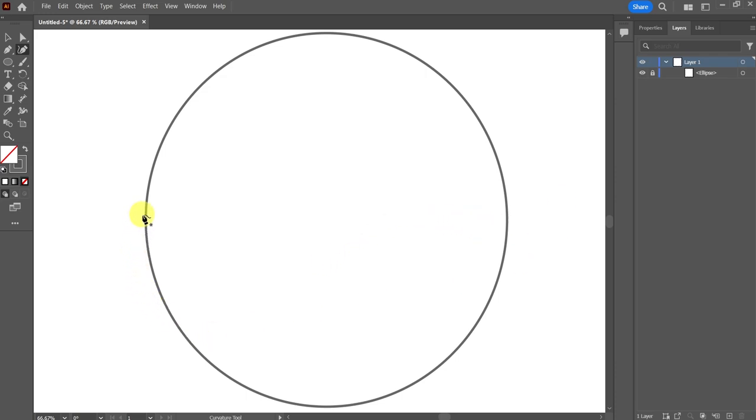First thing we're going to do is make a path right here on the edge of the circle. I'm going to click here, and then we're just going to come out a little bit on the circle and click another point. From here, you will notice a blue rubber band preview of the curve before and after a new point. This tool works by creating anchor points where you click. The path will then flex around the points dramatically. From here, we're going to go out just a tad bit more and create another point. You can also click and drag to make the line more curved, like you're liking, as seen here. And we're going to go ahead and get to the other edge of the ellipse, or the circle.